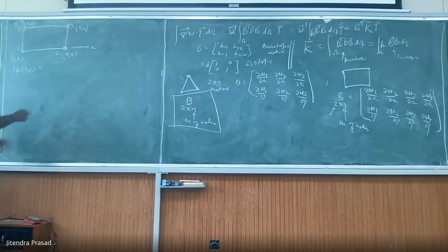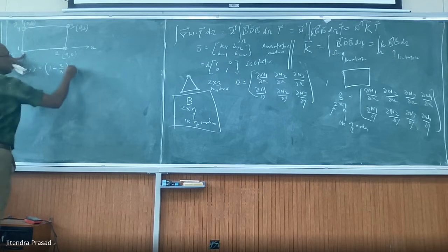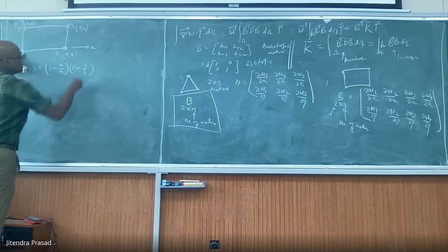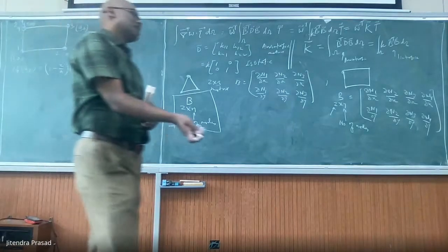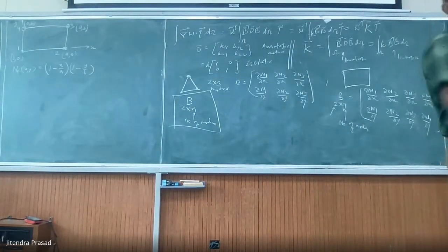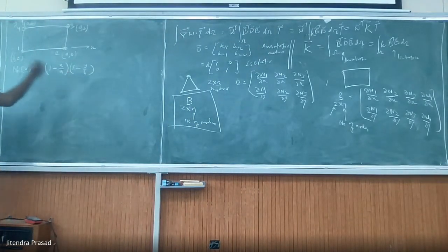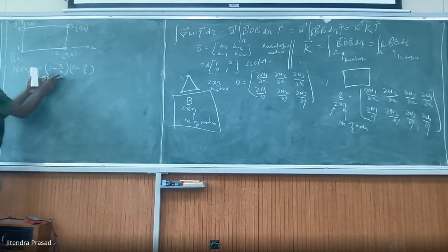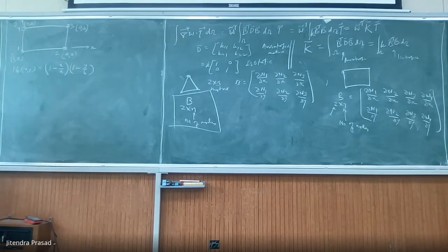And in this case, it will work, and that is you will have from here to here, so it will be 1 minus x over a multiplied by this, so it will be 1 minus y over b. So this will also work. Here you don't have to scale, right? See, it's already there. If you put x equal to 0, y equal to 0, it is already equal to 1. It's already a scale. What we have done? 1D this side, 1D that side. We multiplied, you get it. But it is not always the good thing to do.